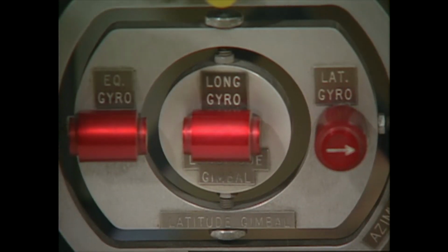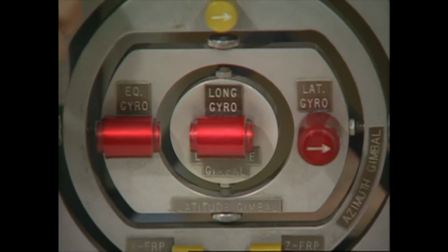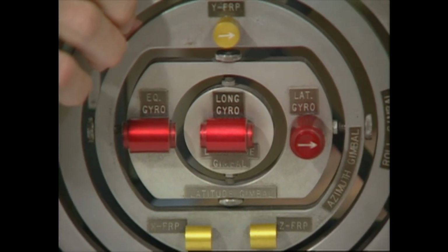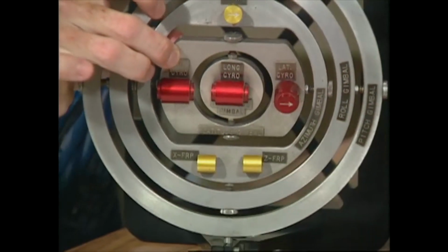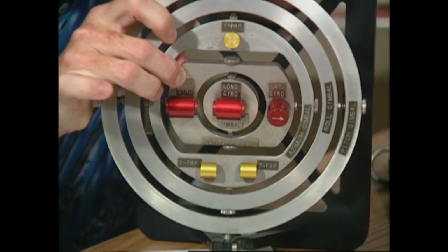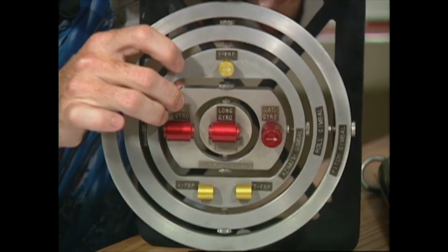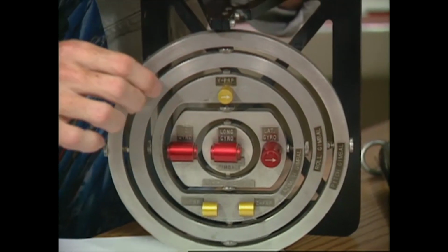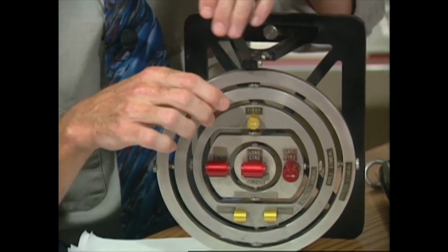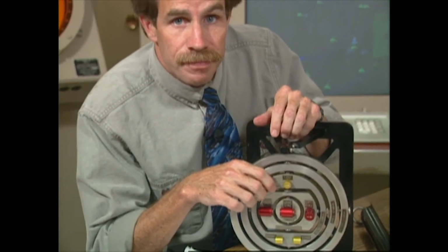Essentially, in an older system such as this gimbal-based system, what would happen is that if the platform rotated, if the vehicle rotated, the gimbals would adjust and keep the accelerometers oriented north, east, and down. Nowadays, it's more common to do that computationally. So basically, all the sensors would be fixed in what we call a strap-down inertial system.